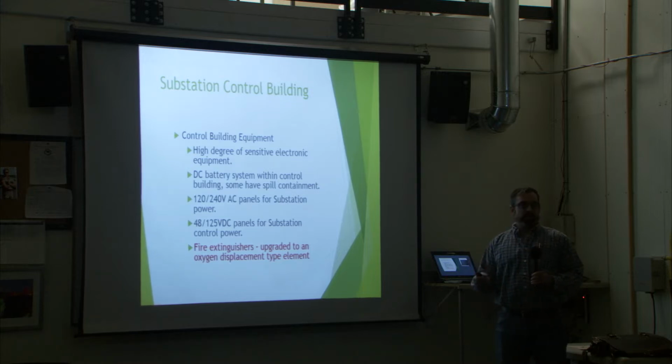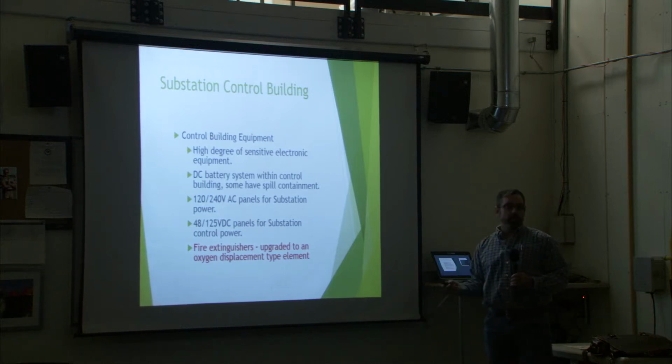But these extinguishers are designed to displace oxygen. We need oxygen to breathe, obviously. So when you utilize these extinguishers, just give a couple short, quick puffs at the fire. If it doesn't go out, please get out. Because remember, when in doubt, get out of the substation or get out of the situation, because extinguishers aren't designed for total fire containment. They're designed to save you, get you out of the area, and then let the fire department do what they need to do.